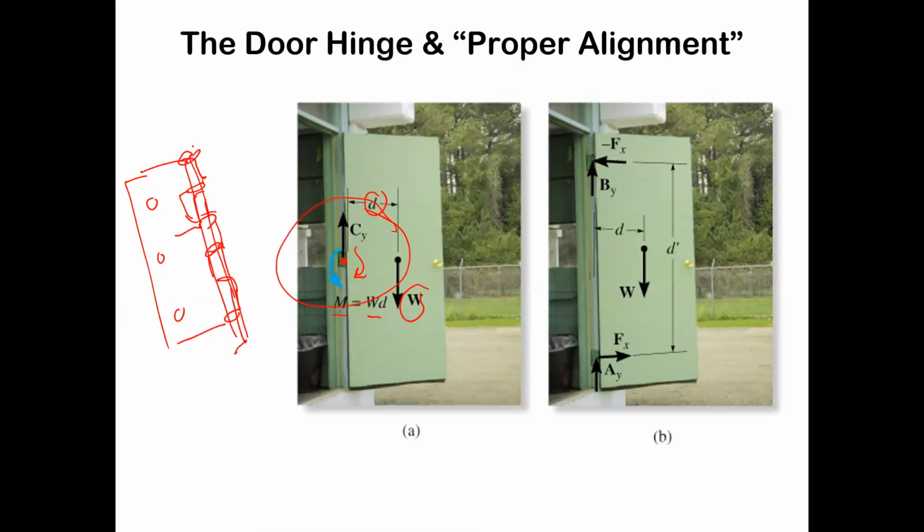So if that hinge is going to provide a moment, what's going to happen is there's going to be a sense of the interlock portion from the other side of the hinge trying to rotate out of that thing, and the pin is going to have to push back with a force that way and a force that way on that side to keep that thing from rotating, right? And that's going to really jam up that hinge pretty bad, right? So the hinge isn't going to actually work too well. You shouldn't put that kind of stress on it.